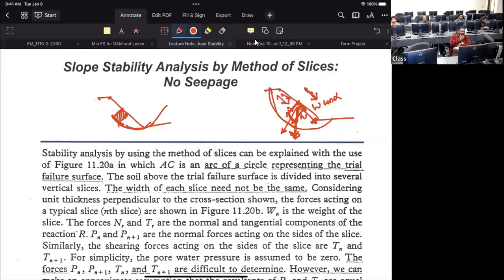That is why Mohr circle is important, isn't it? That's why the Mohr circle was developed, right? You want to distribute between the principal stresses and the Cartesian ones. So any other plane from the principal stress, you draw any plane and you want to calculate that, Mohr circle is the graphical method to do it.